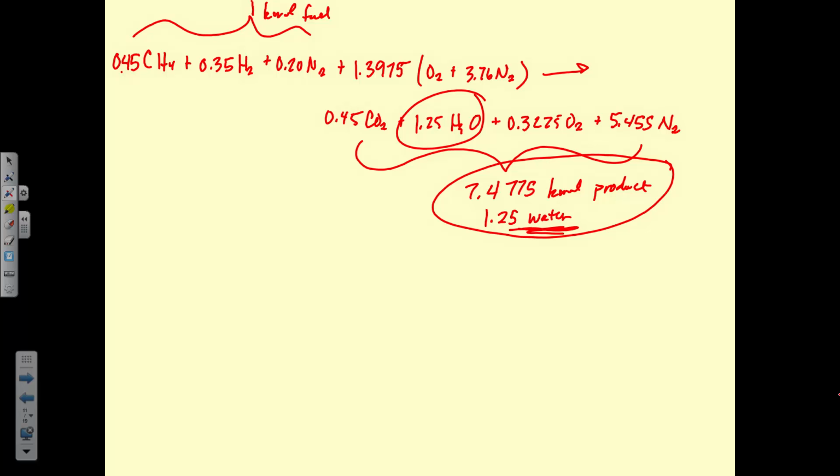If we had a stoichiometric chart for this particular fuel, we would be able to just use a chart. But this chart is for air. We can't use that chart and look up the values, so we have to do it another way. But some of the same principles apply. We can still assume that this is an ideal gas. So one thing that we can assume if it's an ideal gas, from chapter 13, is that the ratio of the pressures is equal to the number of moles over the total number of moles, because we're considering them both to be an ideal gas.